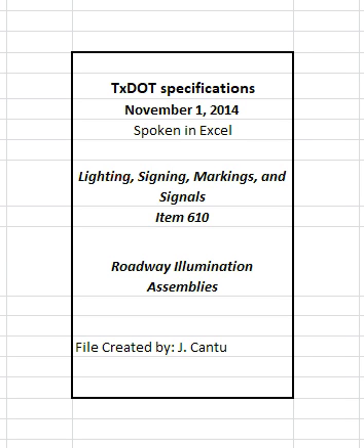Erect structures after foundation concrete has attained its design strength as required on the plans and item 421, hydraulic cement concrete. Tighten anchor bolts for poles with shoe bases and concrete traffic barrier base poles in accordance with item 449, anchor bolts. Do not place grout between base plate and foundation. Test installed roadway illumination assemblies in accordance with item 616, performance testing of lighting systems.